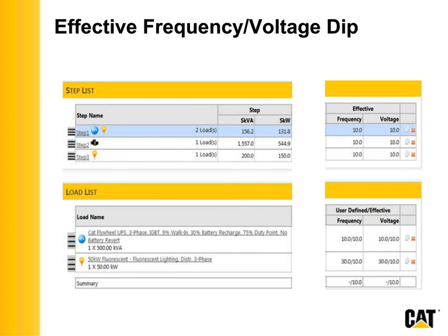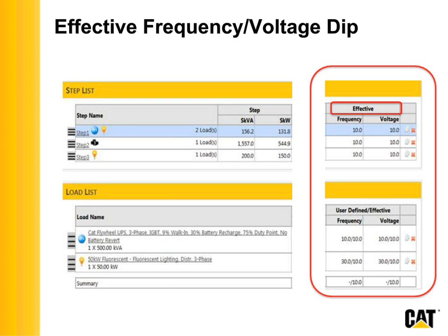Here we're also, I just talked about this. I talked about effective frequency dip and voltage dip. That's the restrictive dip. It's important to understand that a couple of things here are really important about sizing your genset. I'll talk more about this later, but you don't want to sequence all of your loads into one load step if possible.